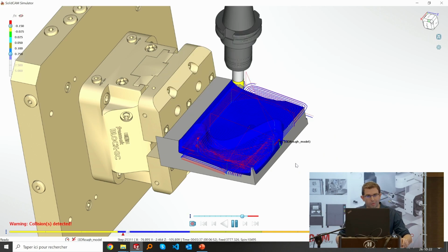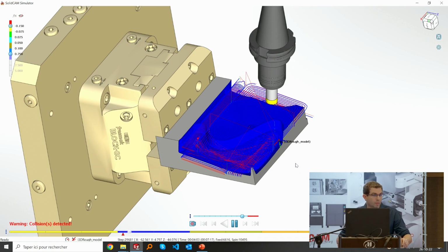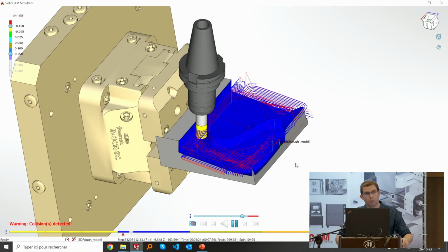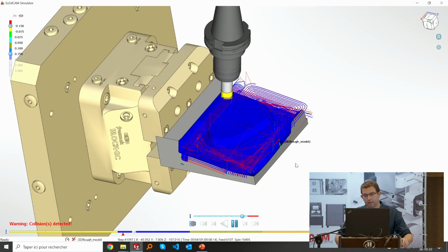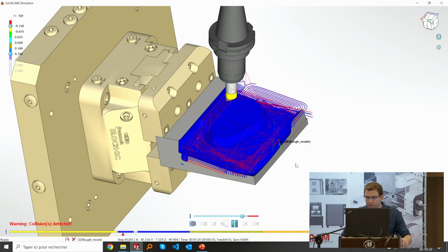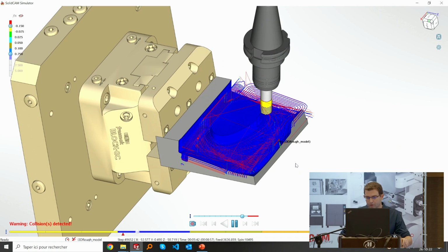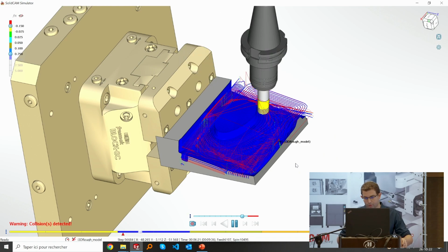We heard a lot about it, and we need to remember that iMachining is what brings SolidCAM users and customers cycle time reduction, thanks to the ability to generate a constant cutting angle. So we get constant cutting force, and it allows us to take very deep step downs.